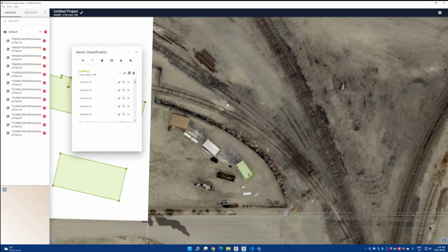And in the screen that we're looking at right now, if it is buildings I'm looking for, and let's say I just missed those two, can I add them as well? So I can delete, but can I also add? Of course, so you can always create, just like you did when you were doing it manually, you can just click this add new label button and then start dragging or clicking around and double click to finish to create a new building label.